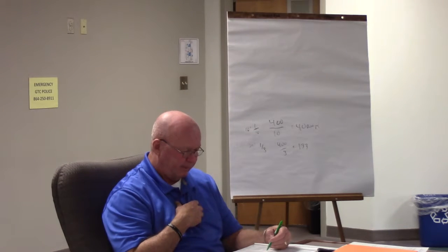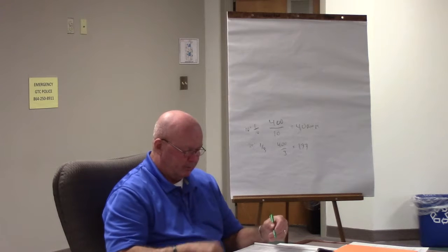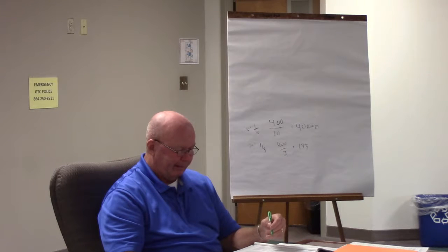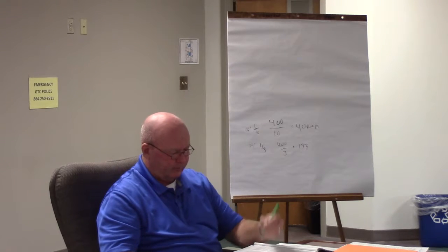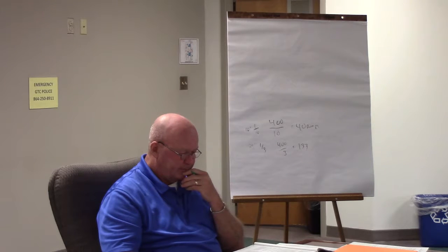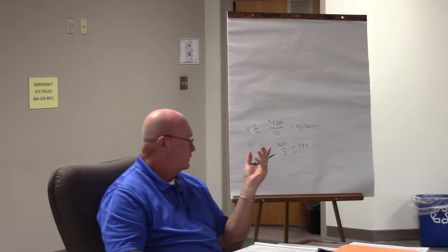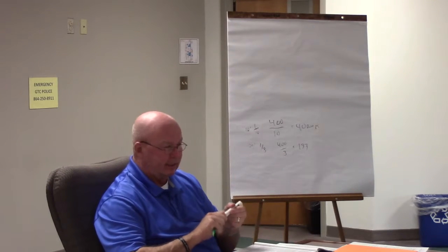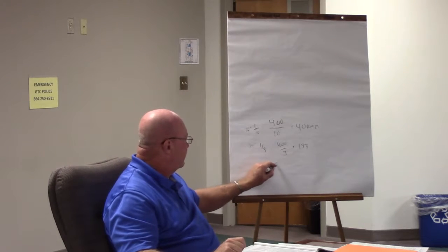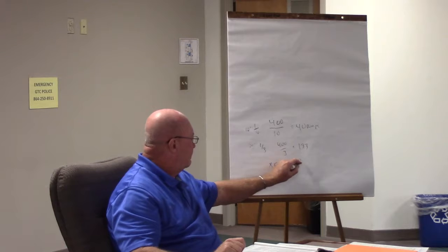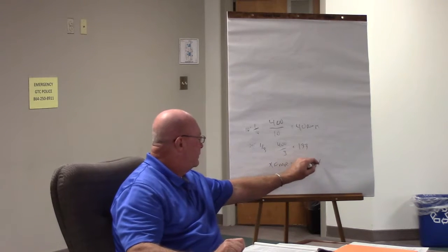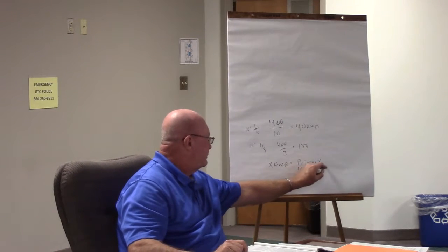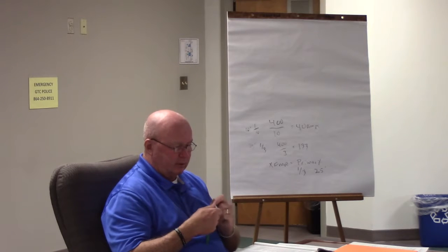Somebody read the first one. Yeah, we're back in the book, because I think it's a little easier to understand it in the book. The primary conductors must have an ampacity that is at least 1/3 the rating of the overcurrent device protecting the primary conductors. Yeah, so did anything change? The only significant word that changed is making sure on the transformer, the rule is saying what's the key word there? Primary, right? And it's still 1/3. And it's 25 foot. Just make sure you understand the wording there.